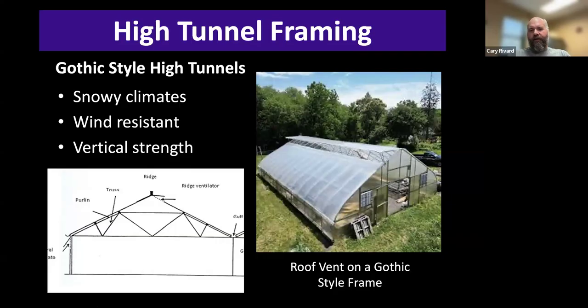It's a really great way to let heat out of your high tunnel or a greenhouse, to let it out up at the very top where it all builds up, right? And you can imagine, thinking about that picture we showed earlier, the convective movement of that air coming in the sidewall and then pushing that hot air out the top can be really, really effective. So I'm a big fan of the roof vents. We just don't really see them much here because we don't necessarily need them in this part of the country.